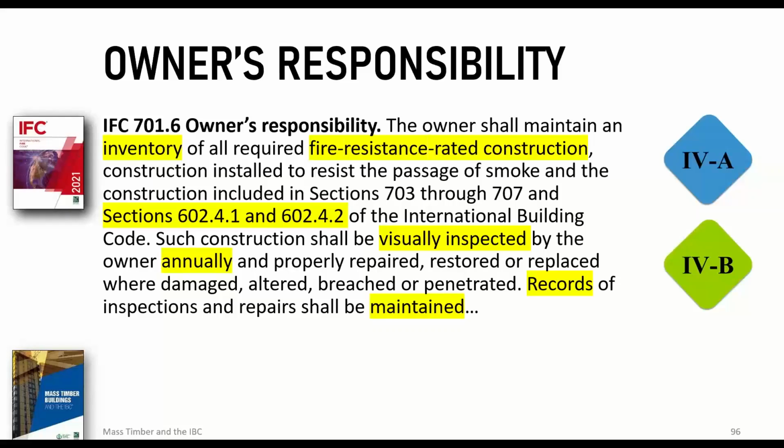As Paul told you, the code provision requires a specified thickness of gypsum board or its equivalent for walls and ceilings in mass timber buildings of Type A and Type B construction, except for limited amounts permitted in Type 4B to be exposed. The allowable heights and areas proposed are based on additional passive protection.